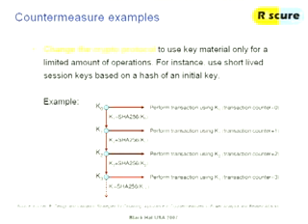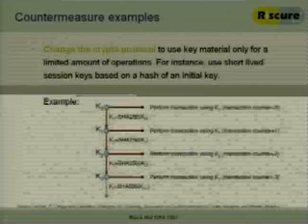So there needs to be some kind of synchronous system so that both sides know at what stage in the transaction they are, to know how to process and generate a new key. But if your SHA operation is leaking, then you'll never leak more than 2 SHA operations. And if that's only a couple of bits per SHA operation that you're leaking, then you'll never leak the complete key. So this is a way to prevent leakage.